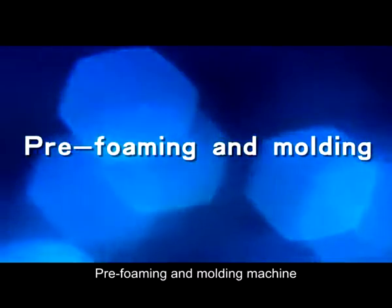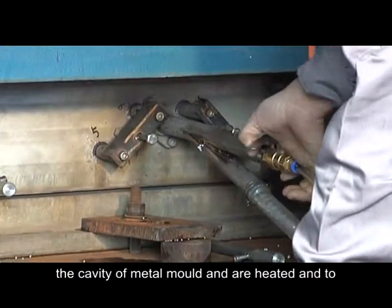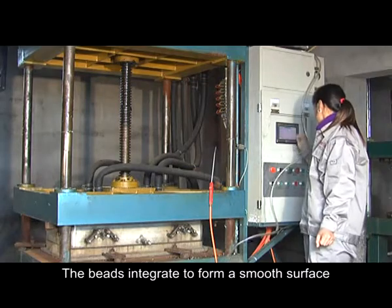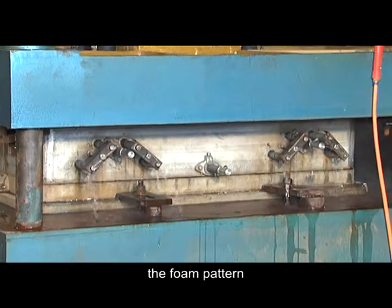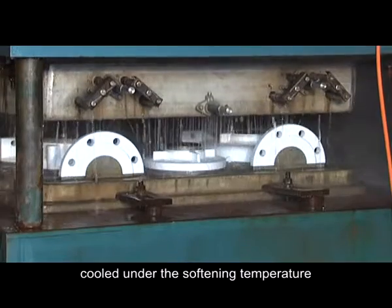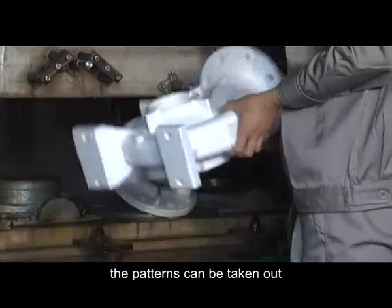Preforming and molding. The preformed and ripened beads are filled in the cavity of the metal mold. The beads will be heated and expanded again, so the gaps between beads are filled. The beads integrate to form a smooth surface, which is the pattern form. Before the patterns are taken from the cavity, the patterns should be cooled under the softening temperature. Only after the patterns are formed and hardened can they be taken out.